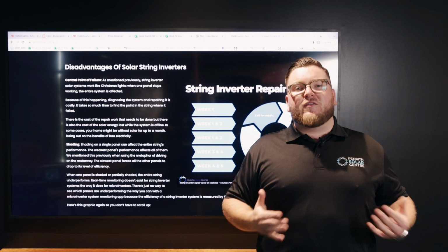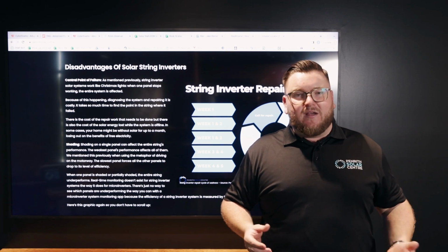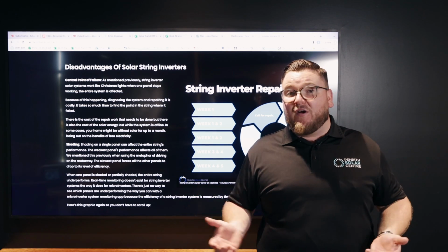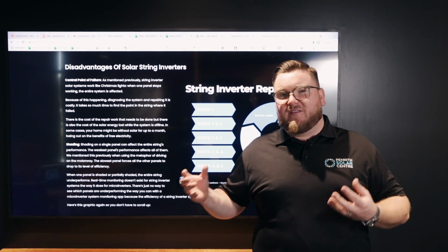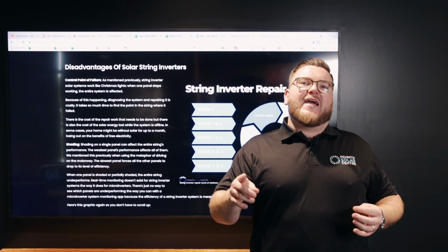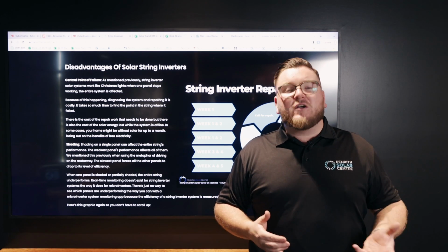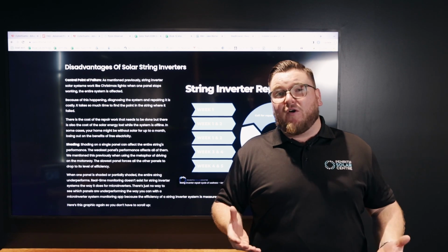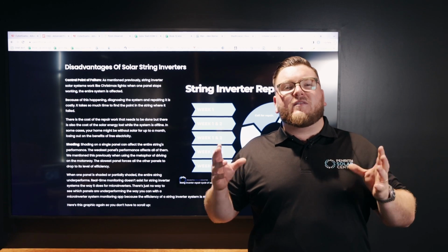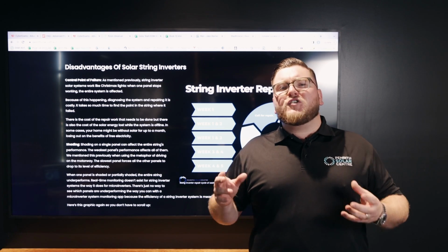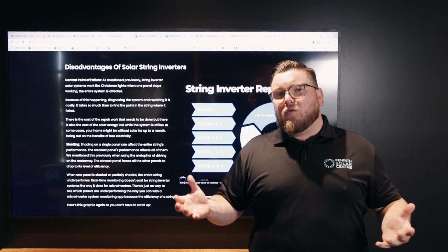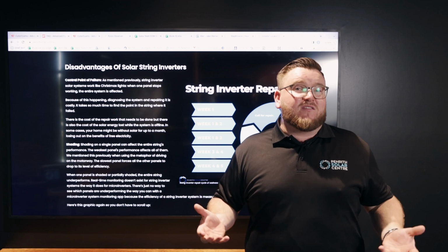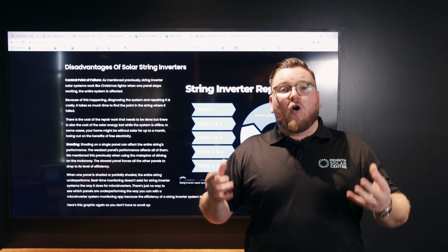All too often at Penrith Solar, we get called out to house fires, isolator fires, inverter fires, and they all have something to do with the system being a string system. Now, it's not really fair to say that it's always the inverter's fault, because usually it actually isn't the inverter's fault. Inherently, when you install a DC string system, there are a lot of cheap inferior components that get bolted to that system, which in electrical terms we call BOS, or balance of system,